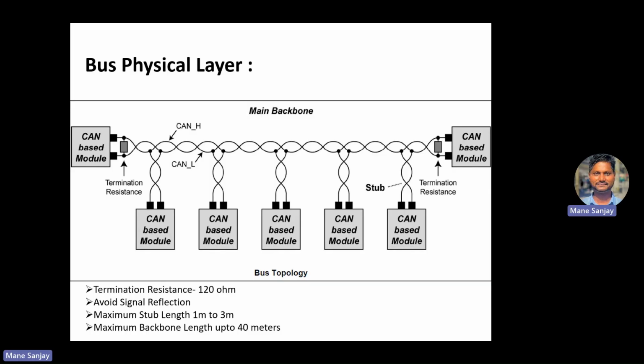And it is practically observed that for coaxial, the termination resistance value is 50 to 75 ohm only, not more than that. It's very common for coaxial termination. For the Cat5 transmission line, it's 100 ohm. For CAN and RS485, it's 120, not more than 120. It is even identified that 100 ohm is a characteristic impedance.